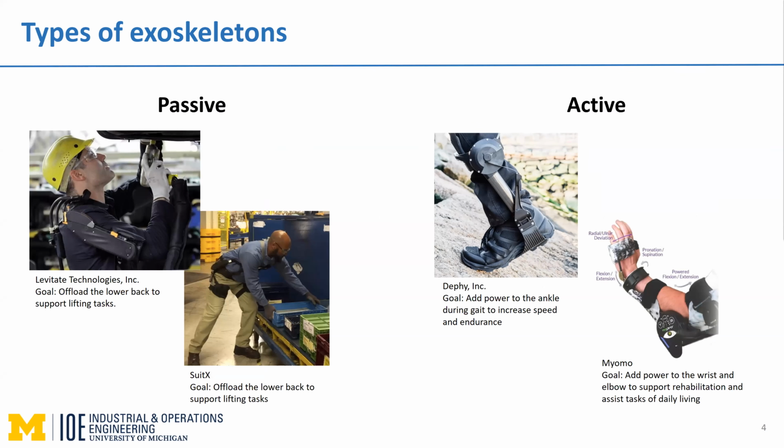So static fit considers the anthropometric characteristics of a user, as well as the sizing of equipment components. This fit characteristic is relevant for exoskeletons that require kinematic alignment with user body segments in order to enable comfort and to prevent injury due to inappropriate application of forces and static postures. So for example, the Lockheed Martin Onyx system shown on the left, the motor needs to align with the knee axis. Whereas the Myomo system shown on the right, the motor needs to align with the elbow axis. Misaligning an actuating component can create undesired forces and moments applied to the person, which can increase risk.